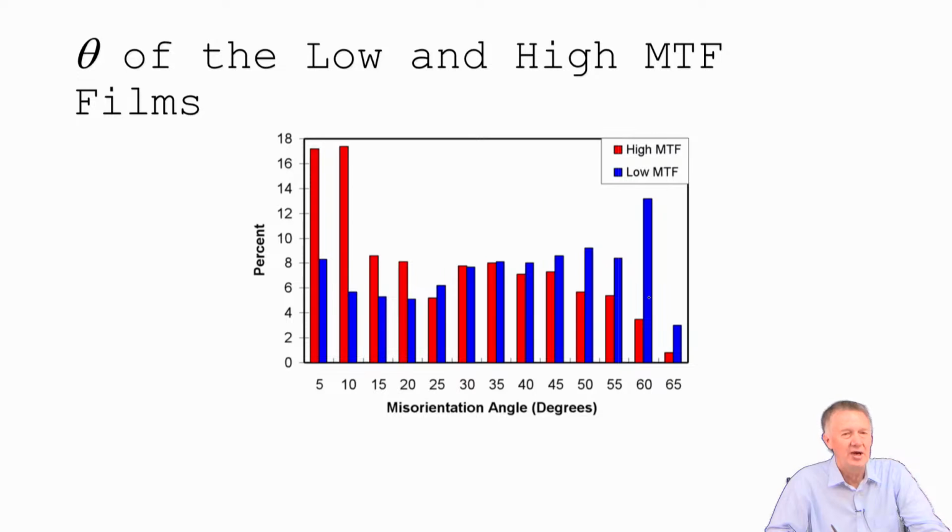Now, if we're describing what actually happens during electromigration in aluminum, where we have polycrystalline lines, it's diffusion along grain boundaries. So that's what's giving rise to early failures. We get diffusion along grain boundaries. And if you have these high angle boundaries that are being shown up here, it's going to be higher diffusion. The diffusivity will be higher in general. Now it's a stress-directed diffusivity. You have an electrical current, 10 to the 6th amps or something per centimeter squared going through that line. But it's stress-directed. But anyway, these will diffuse faster, so you'll have faster failure.